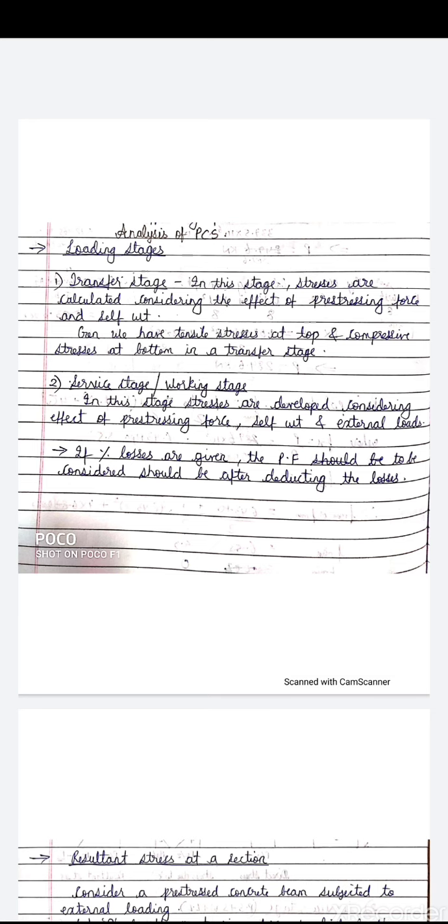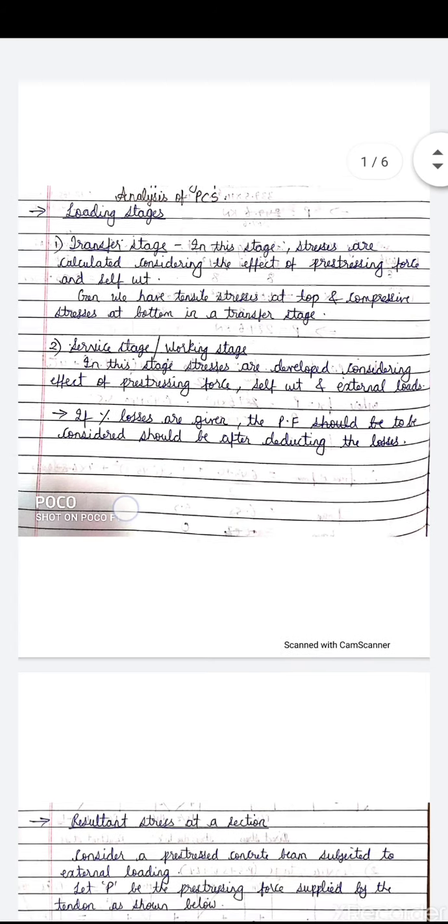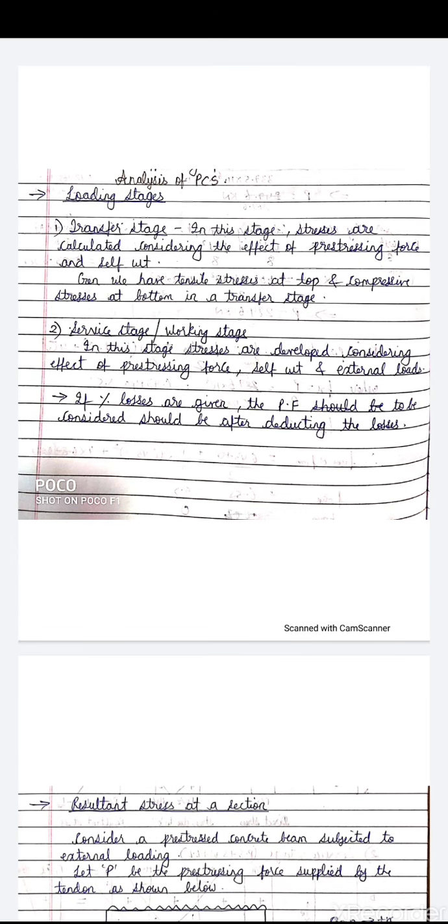So in this stage, stresses are developed considering the effect of pre-stressing force, self weight and external loads. So service stage is nothing but when your external load is also considered, that stage is nothing but your service or working stage. So one note I've written over here, that if percentage losses are given, the pre-stressing force to be considered should be after deducting the losses. So this we will see while we solve the problems.